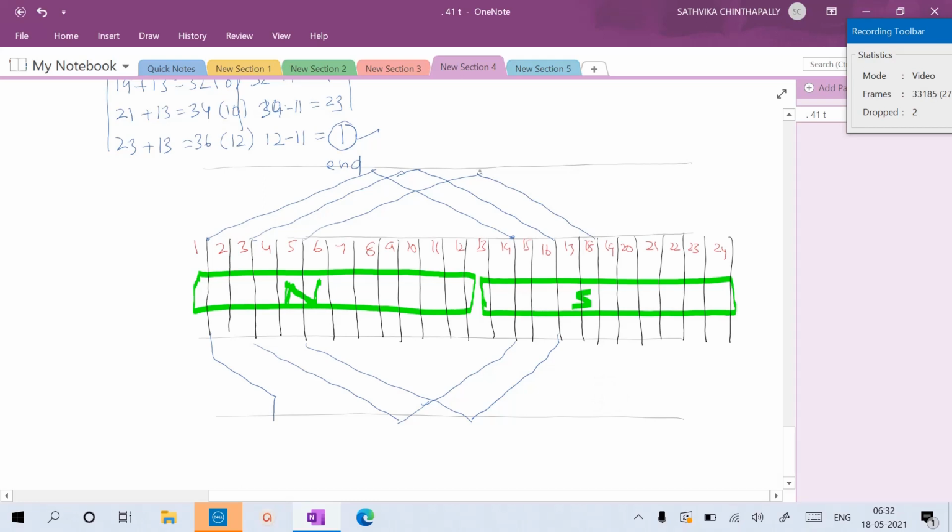Now 18th to 7. Where is 7? This is the 7. You have the drop there, so you can draw neatly. This 7, and this 7 back pitch is going to connect where? That should be connected to the 20th. Now the 20th front pitch you are going to connect to which conductor? That is the 9th, as per the table.